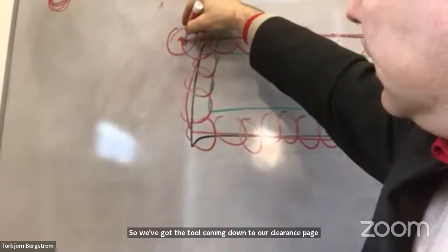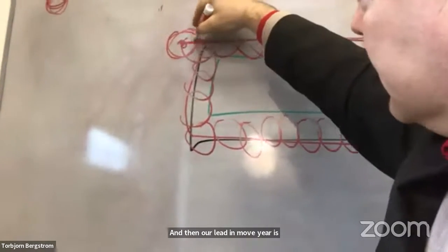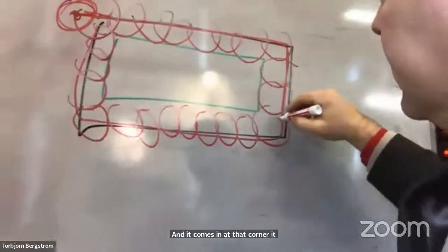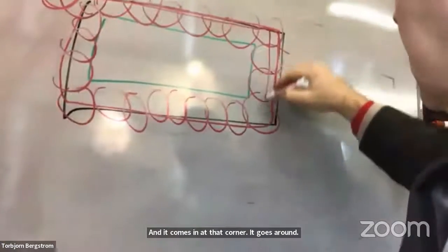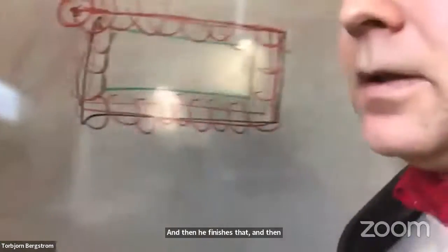And then our lead in move here is tangent to the direction of motion. And it comes in at that corner, it goes around. So I programmed the center line of the tool. And then here it finishes that, and then it moves out tangent also.